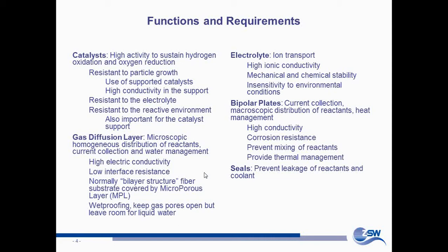So we need to keep the gas pores open, but we also need to leave room for liquid water. That's also important. Liquid water will be present in the fuel cell, and we need it somehow to keep the electrolyte conductive. Then finally, the electrolyte needs to be ion transporting, with high ionic conductivity, mechanically and chemically stable, right?